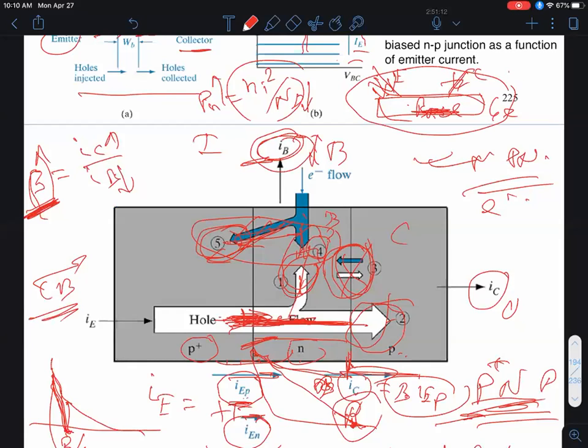Okay, turns out, as we'll discuss in the next class, that's not a very desirable mode, because in this mode, although you can get voltage gain, you cannot get current gain, because you can clearly see that the output current IC is going to be a fraction less than 1 of the input IE if I operated the thing in this so-called common base mode.